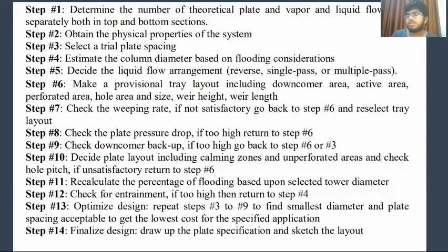Dry pressure drop occurs due to the friction within the dry holes, whereas the residual gas pressure drop results mainly from surface tension as the gas releases from a perforation, because friction will generate and this will give us the residual gas pressure drop. Then the next thing is downcomer backup.